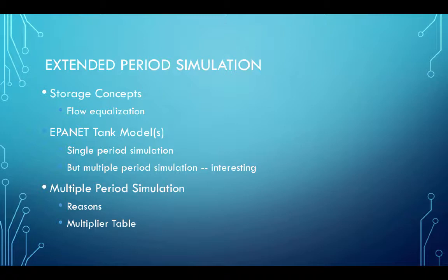So we're now taking our models from a single steady state thing into a series of steady simulations, and that can be used to approximate the behavior of tanks filling and draining, pump performance moving up and down the pump curve, and ultimately, it's necessary for the water quality component if that's something that's important in a particular analysis.